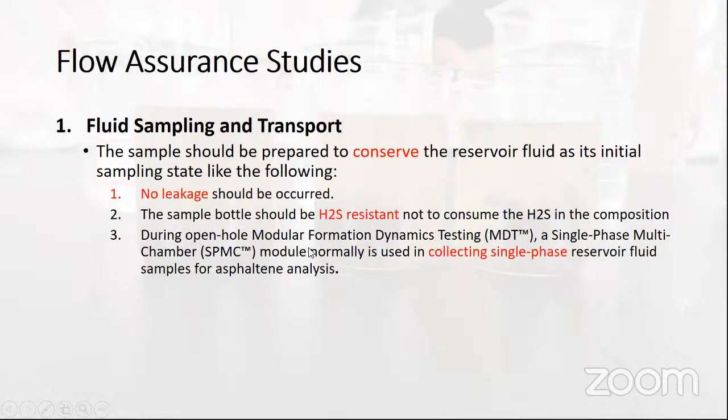Also, if we are studying the asphaltene deposition, a certain type of bottom hole sampling bottle called single phase MDT bottles should be used because it will conserve the reservoir fluid without any deposition of the asphaltene or wax or any other hydrocarbon solid.